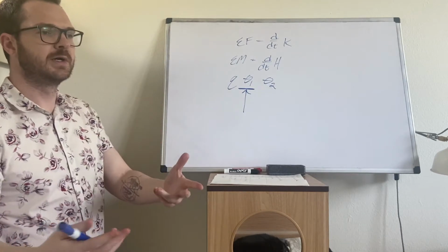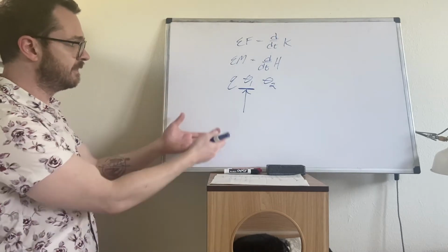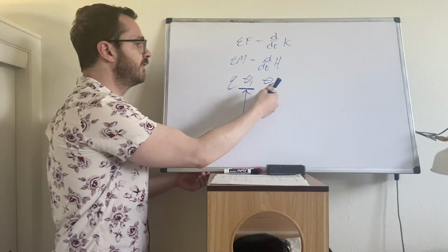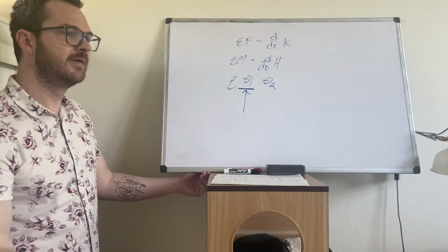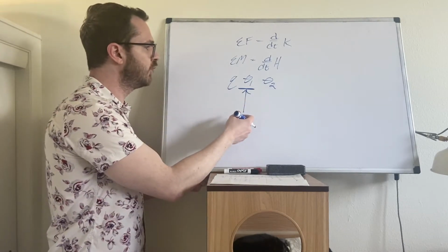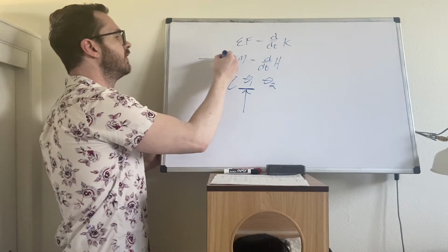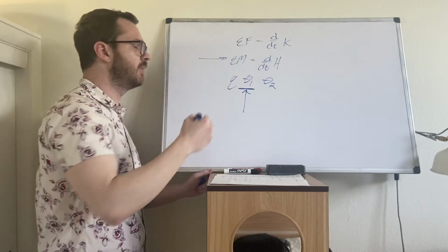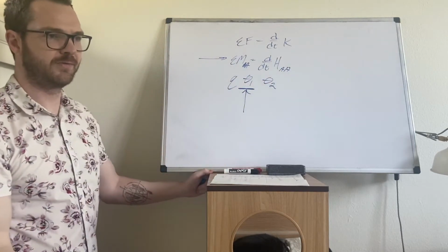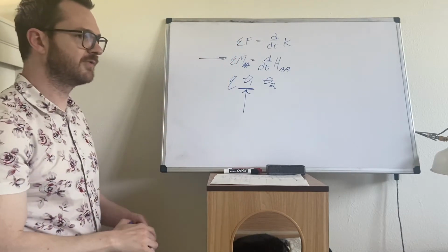What happens if you focus on a different one? You get the same dynamics, right? Those are the dynamics of the system. There's only going to be one set of dynamics. So whether you focus on a different one of these variables, in the end, if you do it correctly, you get the same answer. If we're going to do theta 1, that is the rotation of body A. So that means we should probably do sum of moments on A about A, at least as a starting point. And then we can see how it develops, and maybe we're going to need some of these other equations.